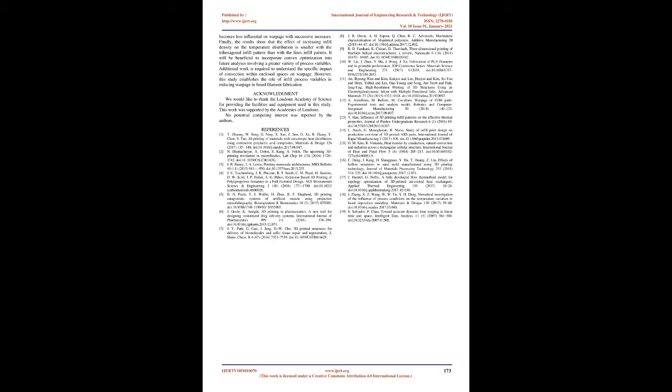In addition, the similarity scores in rows 7 and 8 are substantially lower than the similarity scores in rows 5 and 6, meaning that despite the difference in infill density, the disks with trihexagonal infill pattern were more similar than the disks with lines infill pattern. Therefore, the effect of increasing infill density on the heat flow trajectory is smaller with the trihexagonal infill pattern than with the lines infill pattern.